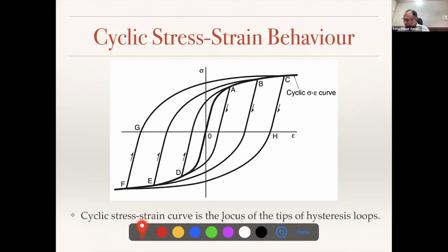So for example, if you take a material, you started from zero strain and you are going for maximum strain here and minimum strain here. So then that particular loop, what you call a hysteretic loop, is for a particular strain, one strain amplitude. If you increase the strain amplitude of the same material, then it will go to B, and so OADA is for one particular strain amplitude,